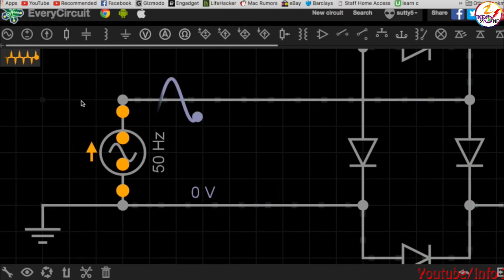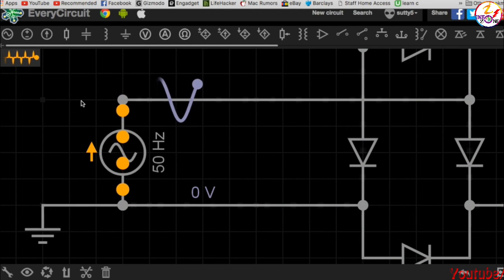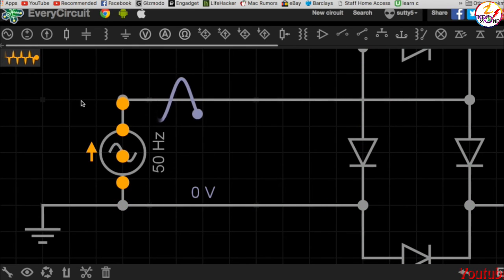They do that by passing magnets through coils. The turbine actually pushes and pulls magnets through a coil, and because the turbine pushes and pulls a magnet through the coil, that is in turn generating an AC current, and that AC current is what's distributed throughout the national grid.